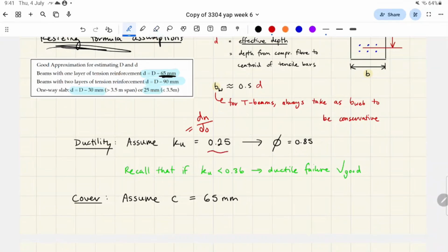Is this the concept that you were saying where you want the concrete to show signs of cracking first before it breaks? Or not quite? Yeah, I mean, it's to do with that. But on a deeper level, when it's a composite section, that only happens because the steel is there and the steel yields first. Because if you have concrete that's not reinforced, it cracks and that crack propagates exponentially, so it essentially breaks straight away.